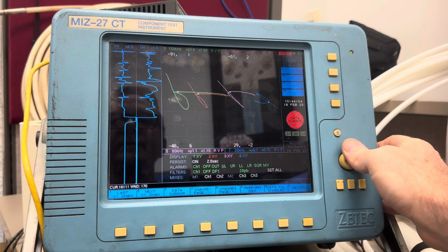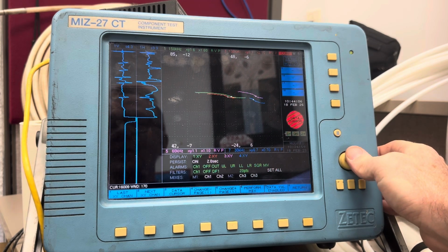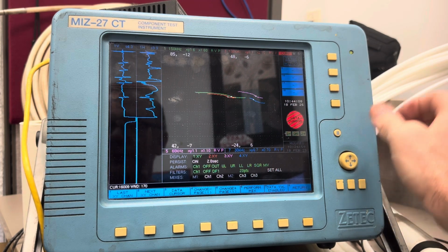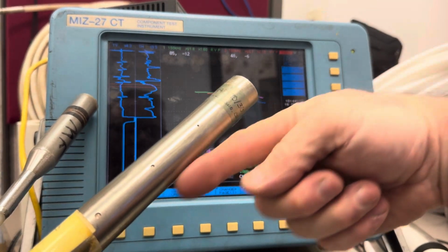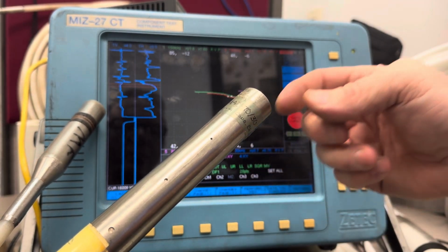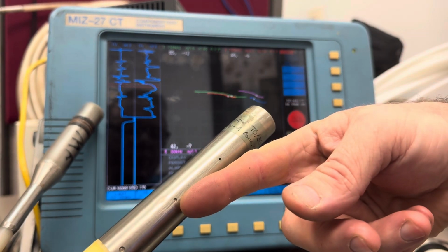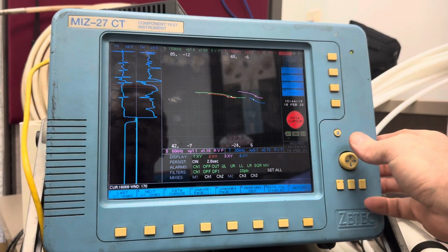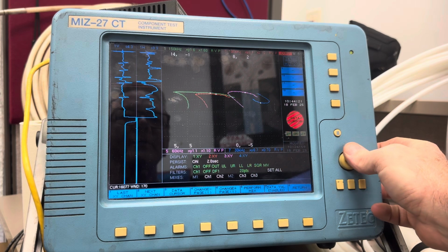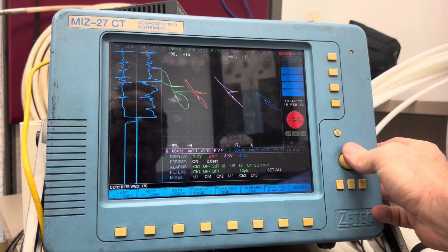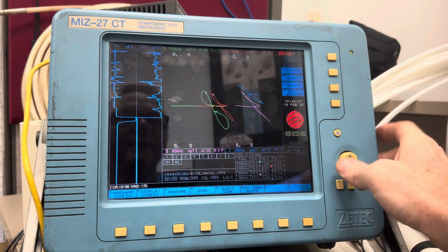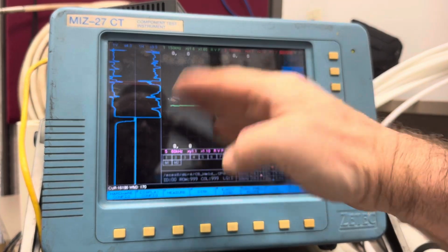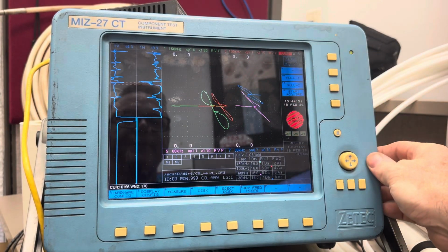And now what I'm going to do is go to the thing that's next to the 100 hole. So there's a 100% hole right there, and I was pulling the probe through this way. Always record on the pull. The next flaw is the 80% flat bottom hole from the OD. So let's look what happens to that phase. That phase is rotated. It's got more phase lag on every channel.